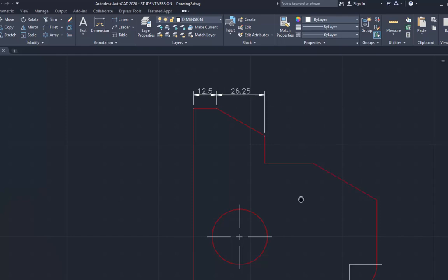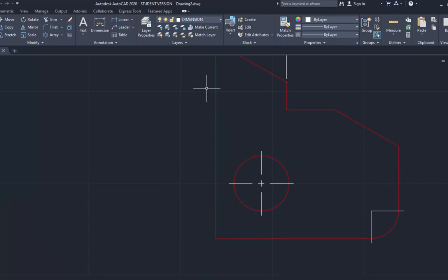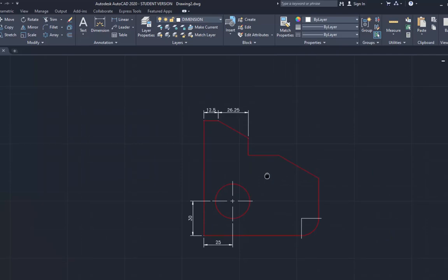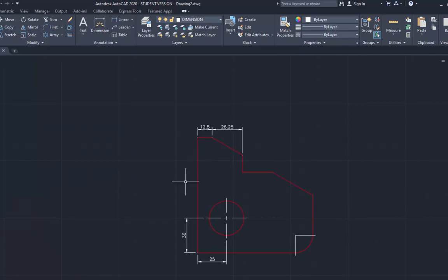Okay, so that it always aligns. Another place where that's commonly used is to dimension two center lines of objects or features that are within the profile that we're dealing with. So again, from a corner to the end of a center line is the best way to do it. That will give me that dimension there. I can repeat the process again from the same corner but to there, and again this is a linear dimension. So that's the basics of how that one will work. So you go through putting on as many linear dimensions as you thought you needed.